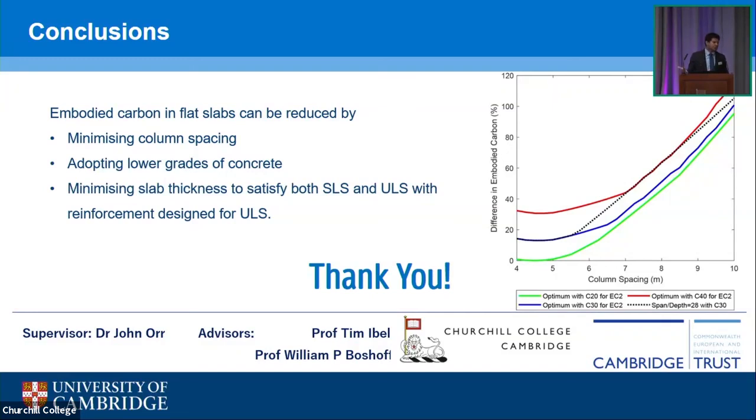but the cost savings sometimes can come from other considerations. As an example, if I'm trying to design a beam, maybe sticking in much reinforcement so that it is easy to bind can be cost effective, but it can be carbon high because of the higher material usage. So those kinds of considerations can be a case where we have discrepancies between the carbon considerations and the cost considerations, but usually in most cases in terms of material consumption, they go hand in hand.